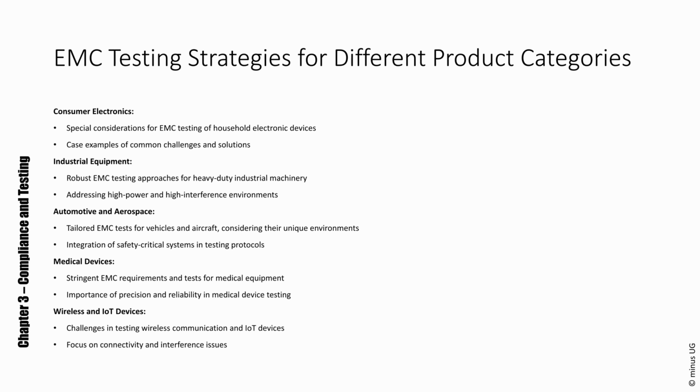Medical devices. The EMC requirements for medical equipment are particularly stringent due to the need for precision and reliability in medical device testing. Ensuring that devices such as pacemakers, diagnostic imaging equipment, and patient monitors are immune to EMI is crucial for patient safety. EMC testing in this sector involves simulating a range of electromagnetic environments to verify that medical devices can operate without interference in a clinical setting.